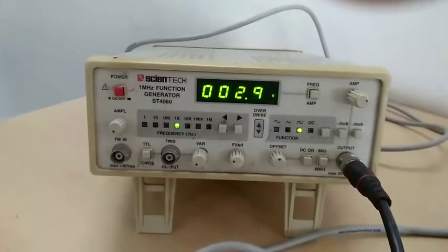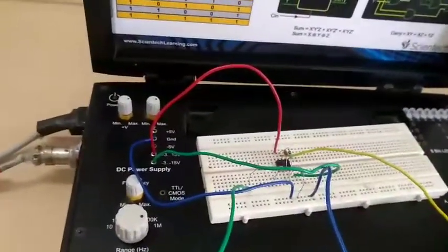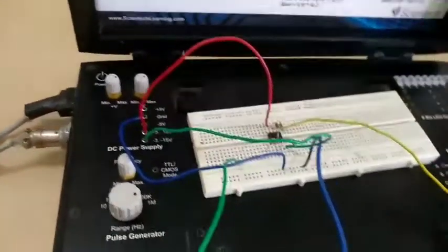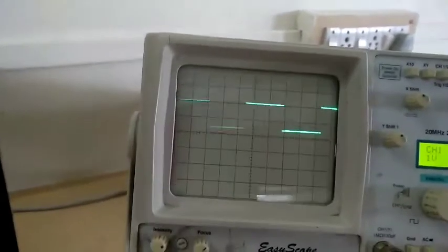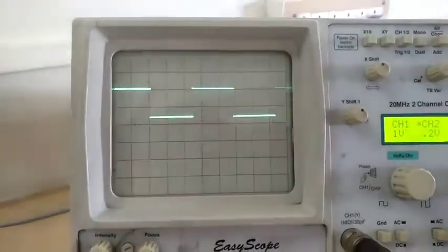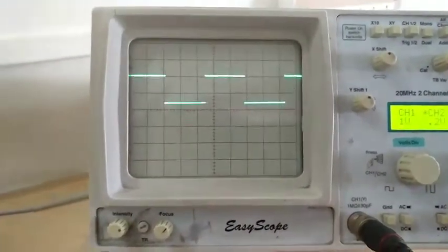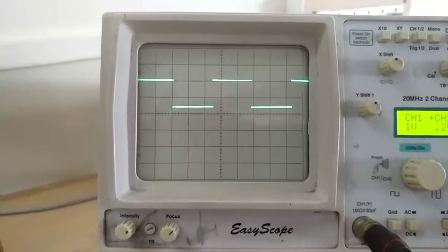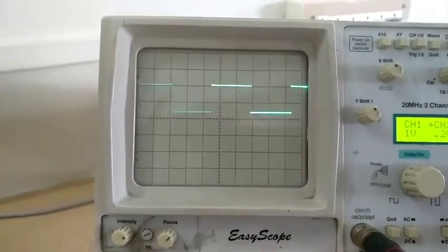So this is the input which is provided through the function generator to pin number 2 of the differentiator, and simultaneously we have to observe the output from pin number 6. This is pin number 6 which is connected to the yellow wire, and it goes to a CRO. So if you observe here, we are getting a square wave as an input, because simultaneously when we are providing an input to pin number 2, a second connection is made and connected to the CRO for observing the input. So this is a square wave as an input.